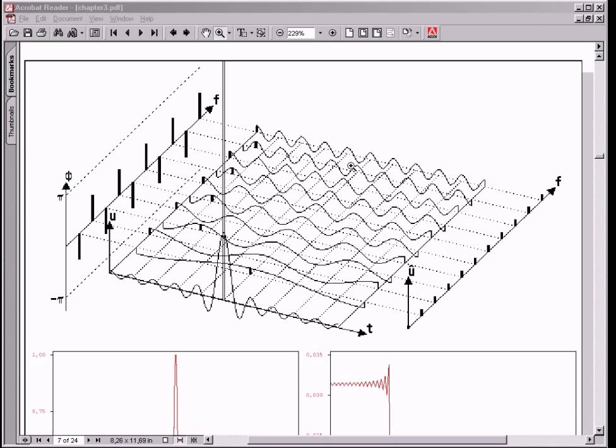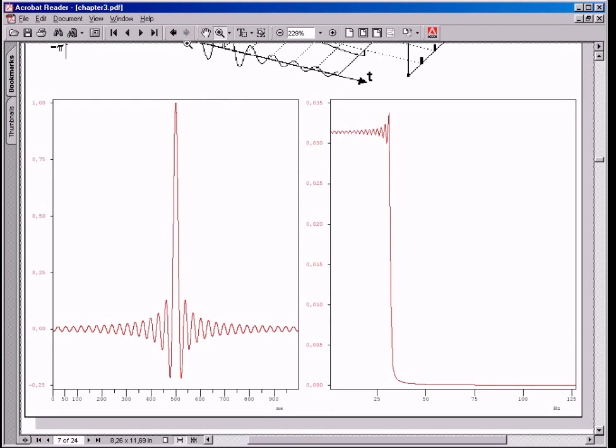In the lower illustration, there is an indication that this cumulative curve reaches far into the past and the future. This would in turn mean that the output signal would have had to be started before the arrival of the delta pulse at the entrance to the filter. This contradicts the causality principle. First the cause, then the effect. Therefore, such an ideal rectangular filter cannot exist.